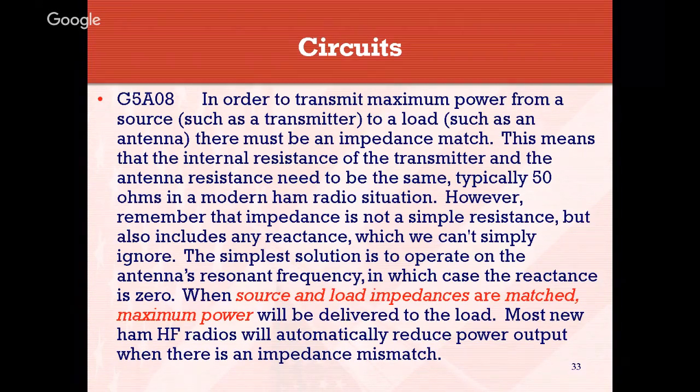This is the central part of the antenna. And now you can actually operate over a little bit broader spectrum on that same antenna, but it'll show you the SWR curve, and also it'll give you a little bit of an impedance indication as well, as it shows that SWR curve go up on the edges.